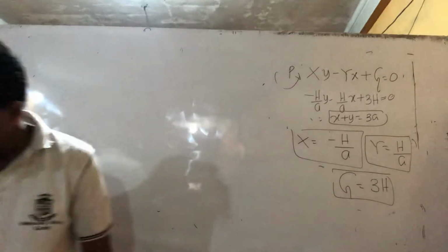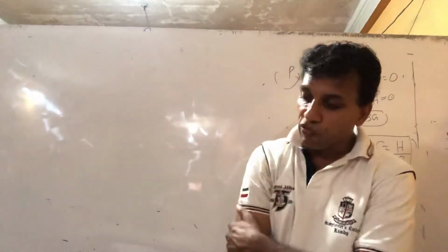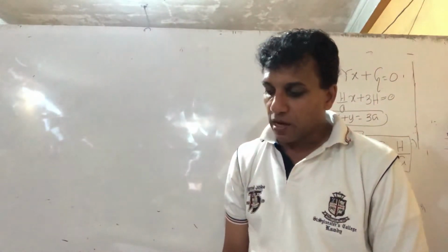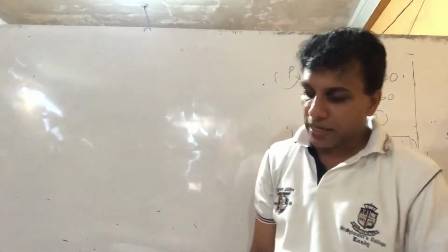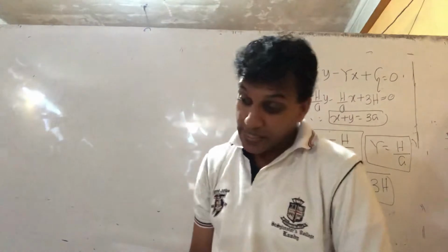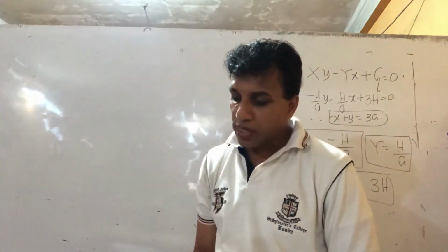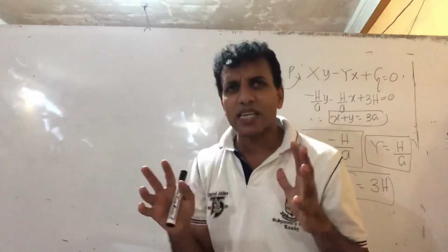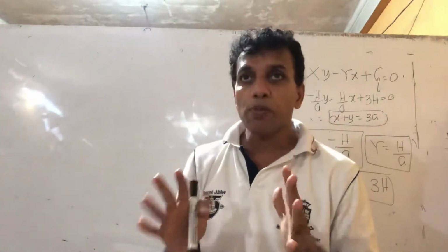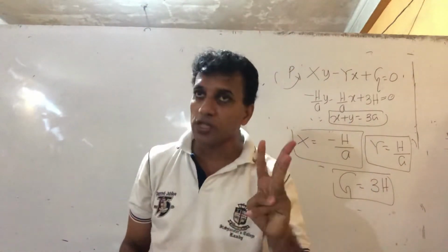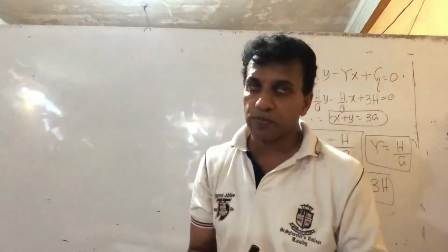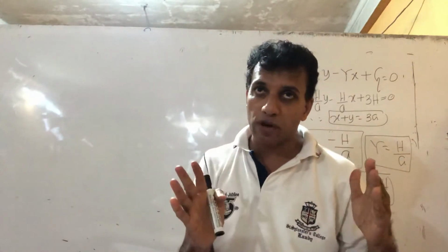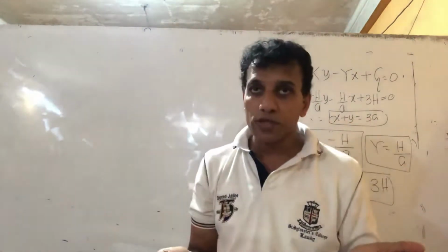They said AB and BC are two uniform rods of weight W which are smoothly hinged at B. When the system is suspended from A, angle ABC makes 90 degrees. The system is in equilibrium by joining the extremes A and C by an inextensible string. So when drawing the static force diagram, the forces should be balanced. For equilibrium, there are 3 forces, and all 3 pass through a single point. The system should be in equilibrium when you draw the diagram. If the system is not in equilibrium, the forces will be wrong.